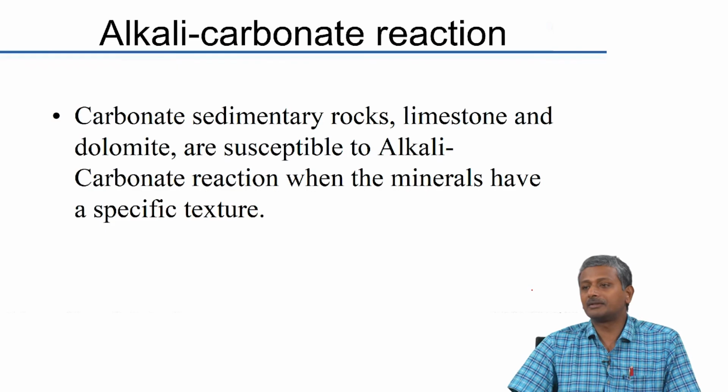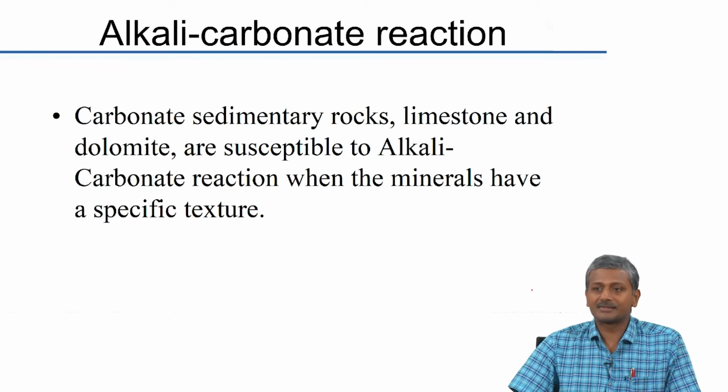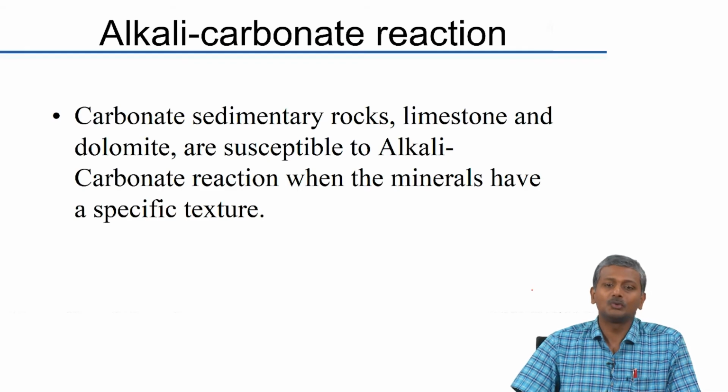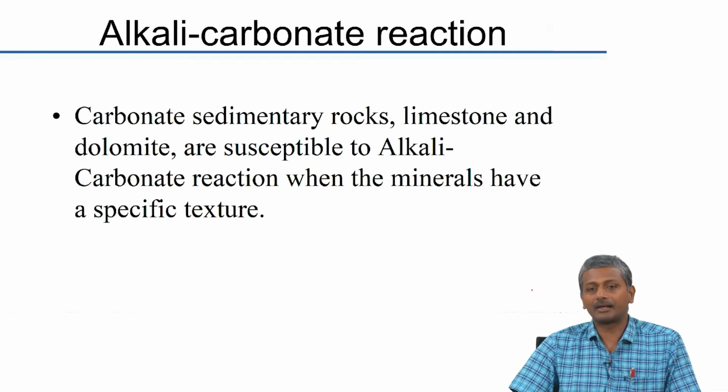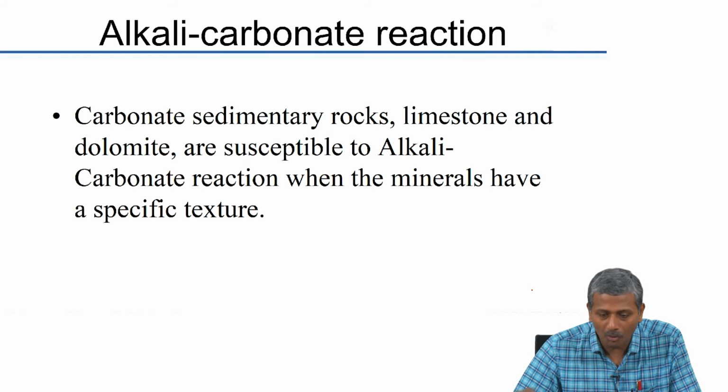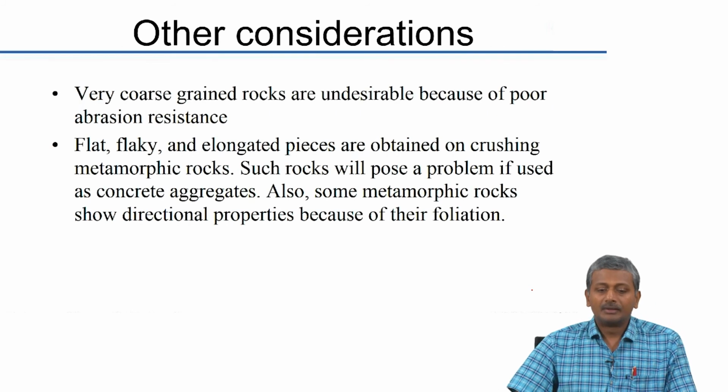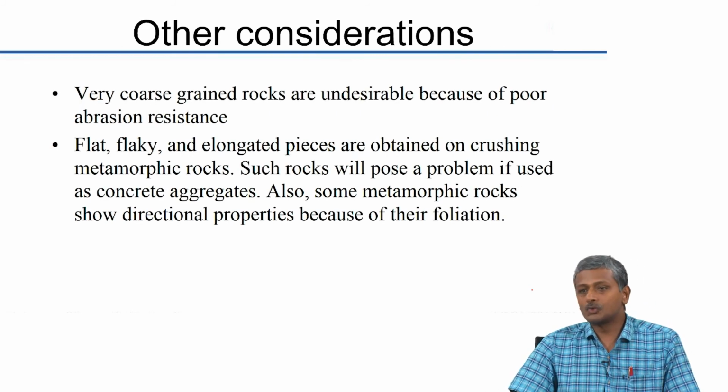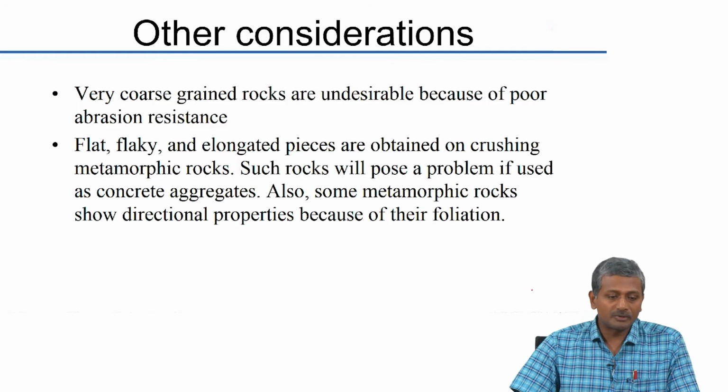But for the most part we know that there are certain types of textures which are exhibited by carbonate rocks which can lead to a high degree of reactivity in an alkaline medium. So, we will not talk about this in more detail. There are other considerations obviously when we choose aggregate for concrete purposes.